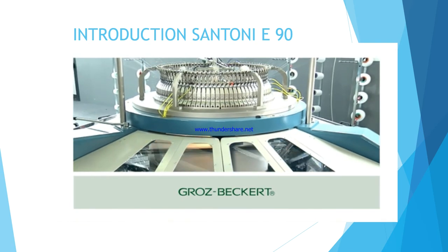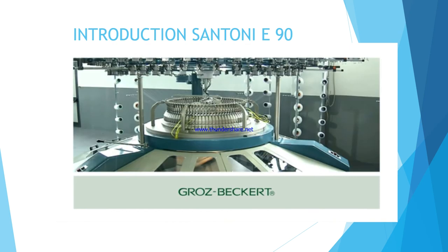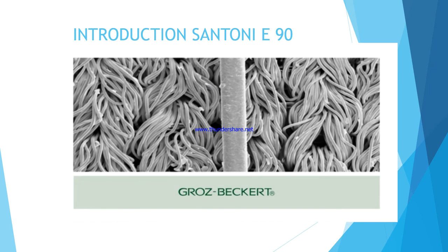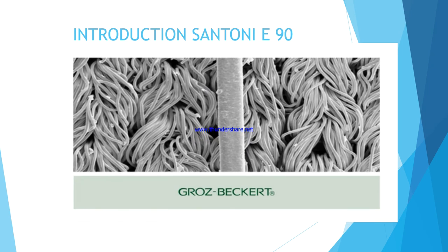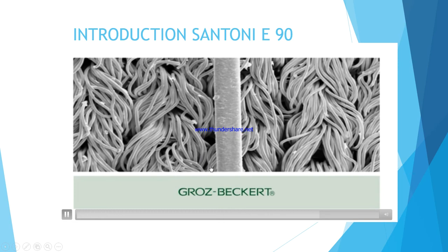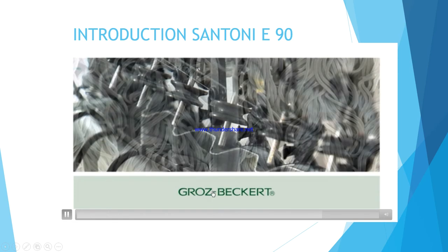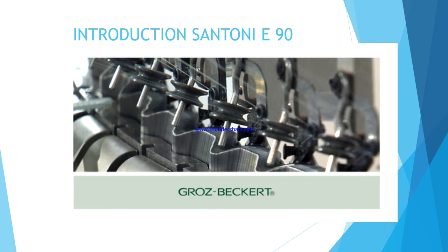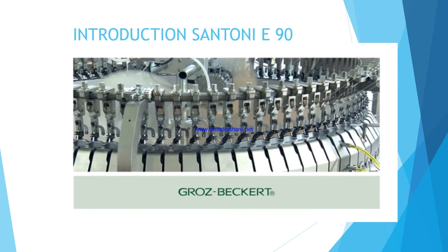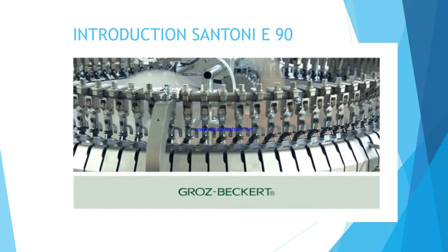The yarn sliding on sinkers in traditional machines leads to bad positioning of the yarns on the knitting platform, with resulting plating defects. The Atlas has proved to be free from this knitting defect, thanks to the fact that after yarn insertion and completion of the loop formation, the yarn does not come into contact with any other element apart from the cylinder. Only after loop formation and stabilization does the holding down jack come into contact with the yarn. In the event of a restart, the holding down jack's presence avoids stitch build-up on the needles, thus preventing breakage.